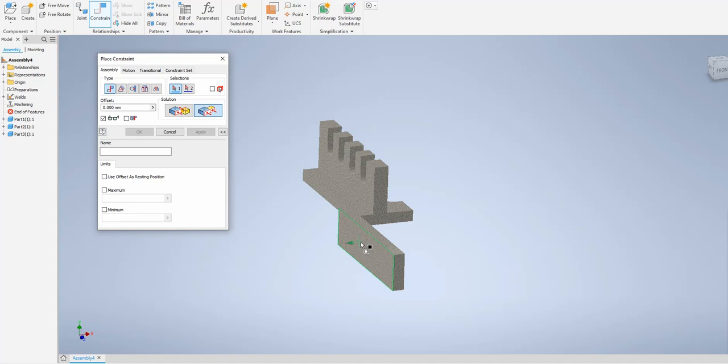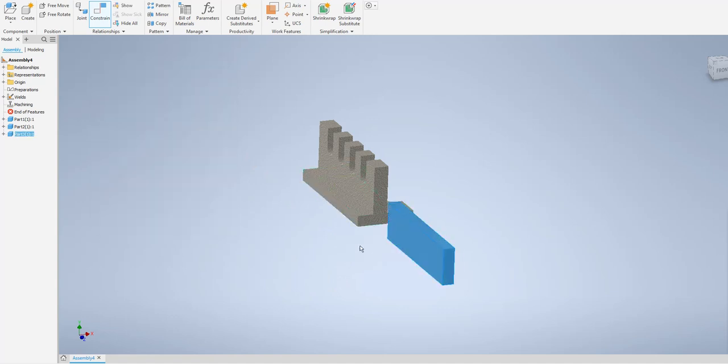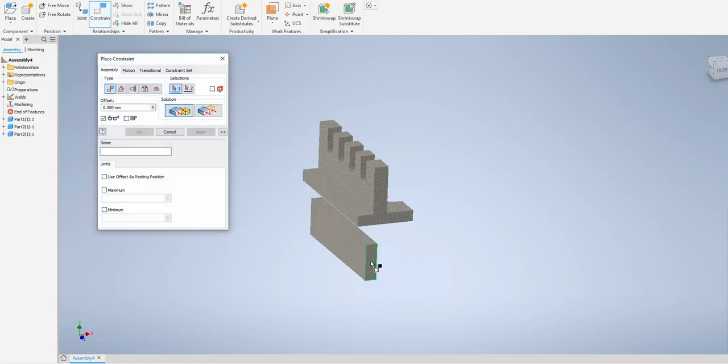Okay, can I use the edge? Yes, you can use, but take care about the welding. When you try to make a groove or chamfer, that edge will disappear. So the assembly was done on that edge, and there will be a problem. So I will choose flush surface, this one to this one, make it parallel without any offset, apply, cancel. Okay, and also flush this surface, make it parallel to this surface without any offset, apply, cancel.